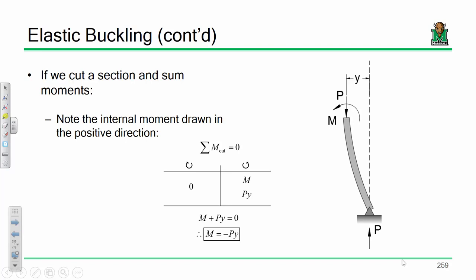So I'm going to have the axial load, but I'm also going to have a bending moment. I mean, the column looks like this. It's being bent, so there's going to be some bending in there. And I propose that bending, just based on the statics, equals the amount of load in the column multiplied by its deflection. So the moment is a function of how much it's deflecting. More deflection equals more moment. And so that changes what our equation looks like here in a second.